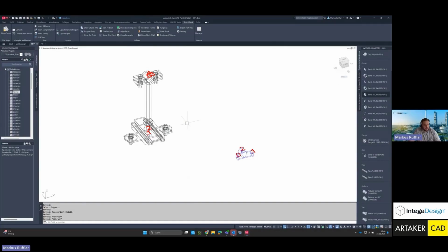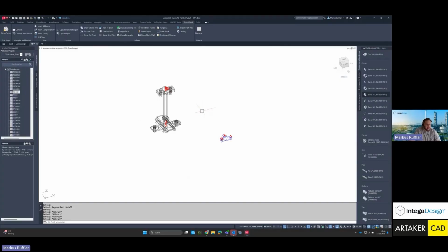Yes. All right, then another exciting feature for all admins is the draw bounding box function. Let's say we have a component now, whether it's block-based or programmed in Python, and we just want to quickly measure its outer dimensions. That's always a recurring topic. Sure, you can determine the flange lengths or the component length pretty quickly, but especially when it comes to height, maybe with a drive mounted on top, then you have to start fiddling around again. You can't just easily snap to reference points. You have to explode the part and so on.